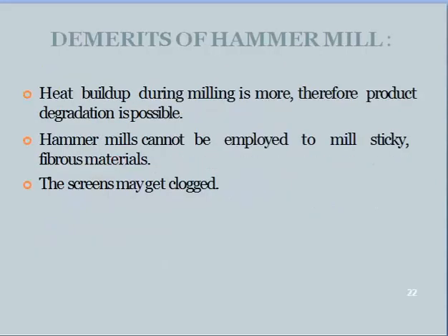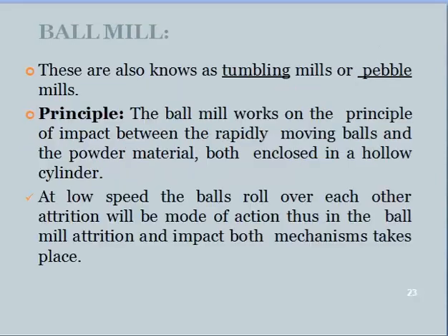Now demerits of hammer mill. Heat buildup during milling is more, therefore product degradation is possible. Hammer mill cannot be employed to mill sticky or fibrous material. The screen may get clogged. These are the demerits of hammer mill.